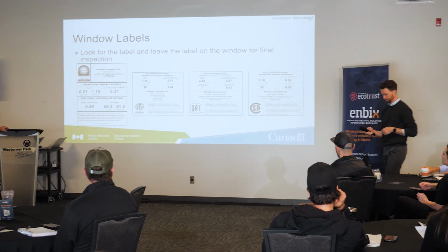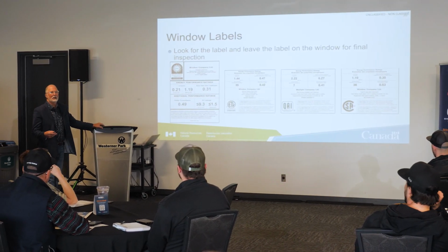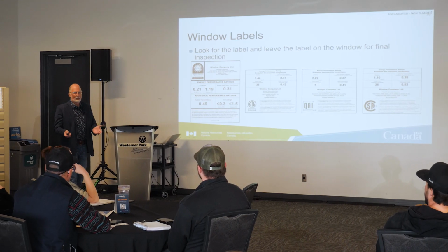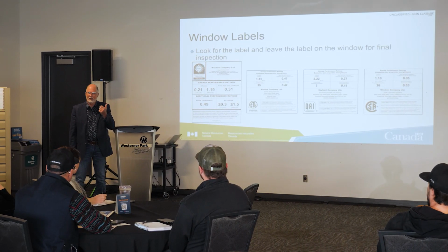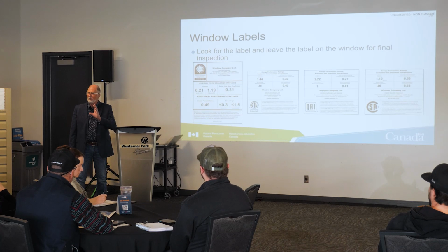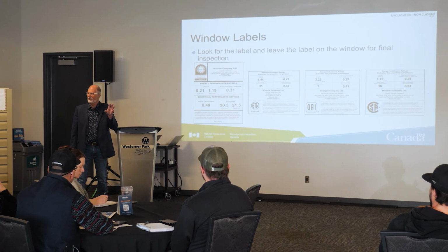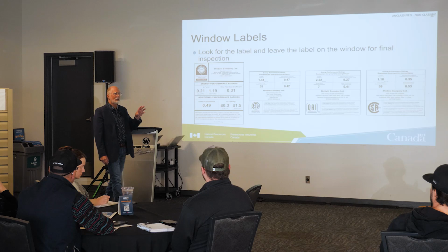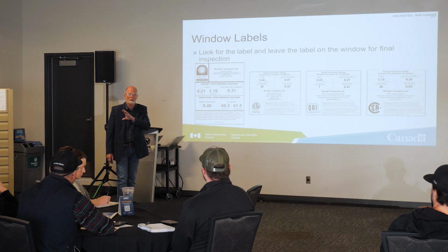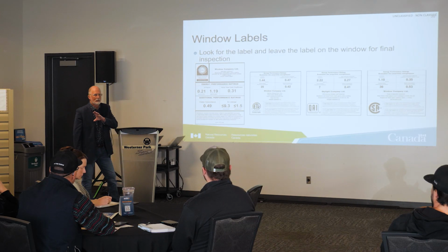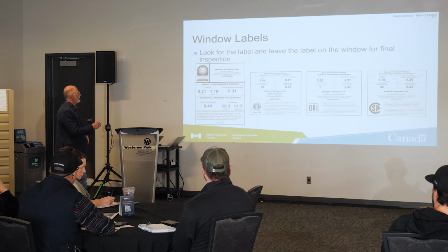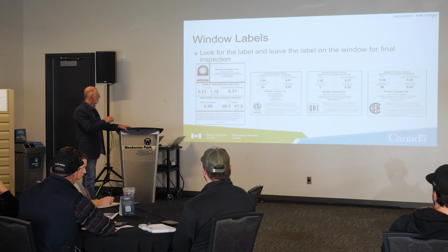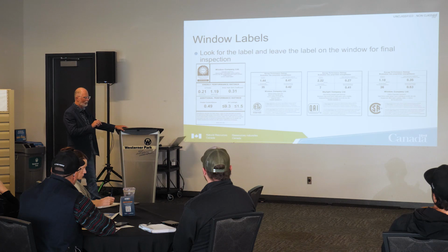Yep, exactly. So it's kind of the same thing when you look at the house as a system, right? You look at your mechanical system, your ventilation system, you know, what's more important, the furnace AFUE value, or the HRV, the percentage of heat loss? Those are two things to look at. And you compare those to windows, we have all these different things on the window label.